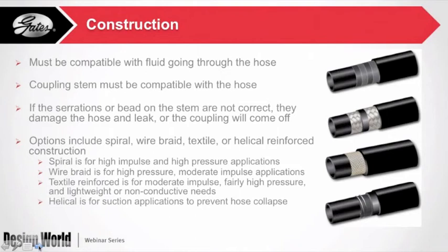And then, of course, the helical construction. The hoses will be built with a steel wire helix or a monofilament helix built into the hose, and that keeps the hose from sucking shut under suction. So we want to make sure that we've got a coupling that's not going to cut that helix, especially if you've got a monofilament helix. If you get the improper crimp information, you can easily damage that helix and expose that opening to a leak path.